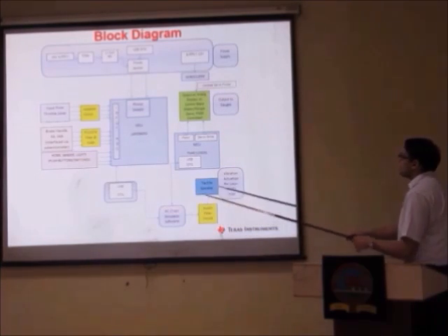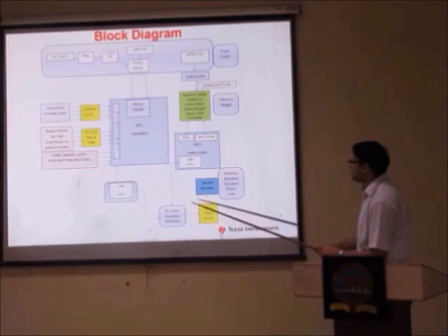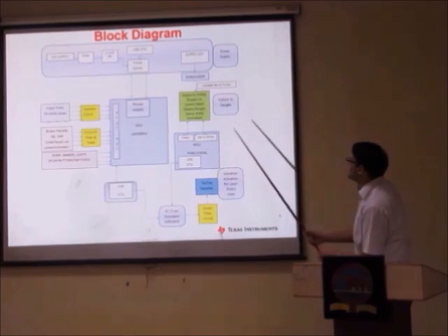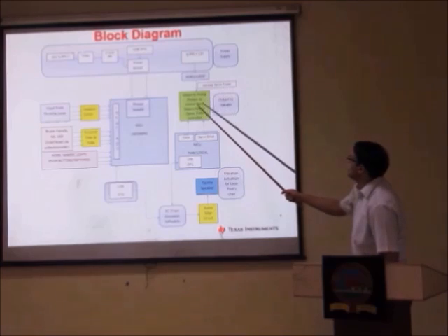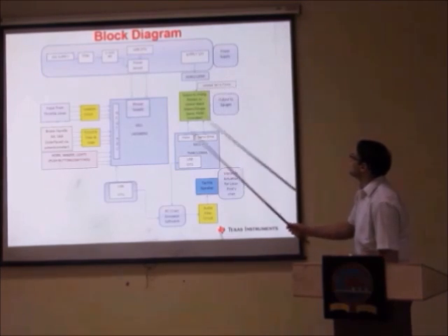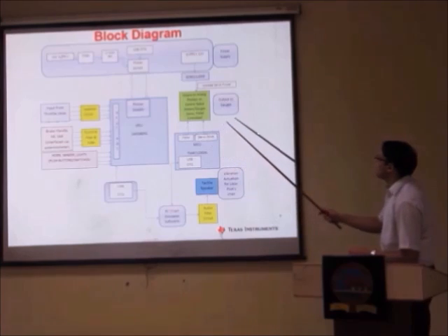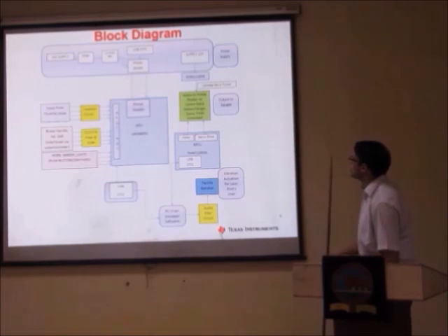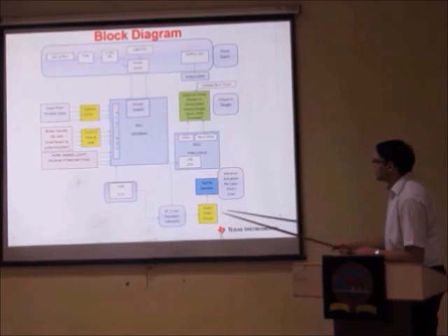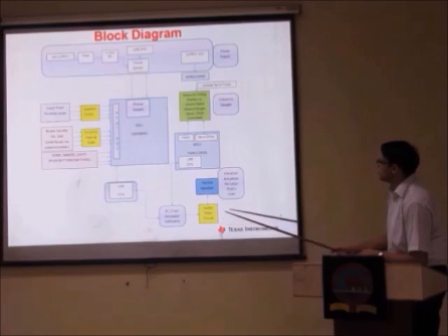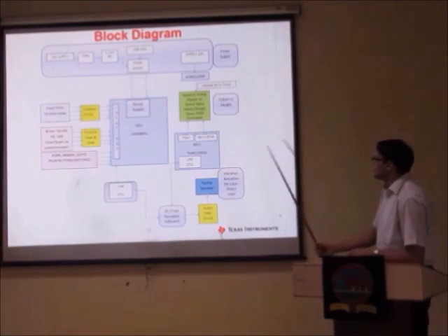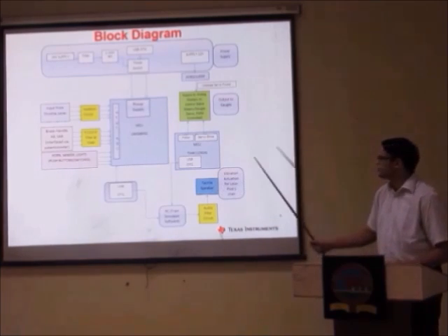From the PC, data is sent to the TIVA C-series microcontroller for driving meters and gauges. We are using a separate isolated power supply for the servo motors to prevent loading on the USB outputs of the PC. We are also using an audio filter circuit, which is a UAF42 filter circuit, for driving tactile sensors for vibration actuation of the loco pilot seat.